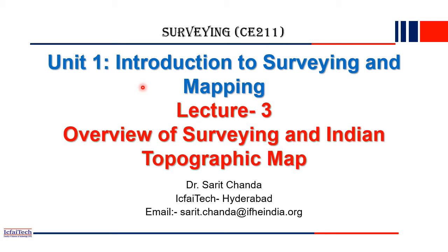Scale is one of the very important parameters while drawing a map. Scale is nothing but the length of a line on a paper upon the length of a line in the actual field. We have discussed that to prepare different types of maps, we normally choose different types of scales as well. So now, if you want to draw the entire country border or country map, a topographic map, where normally we show the hills, rivers, all these parameters, in that case we take a smaller scale, and then we draw the entire plan or entire map.